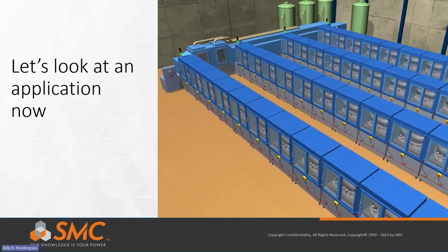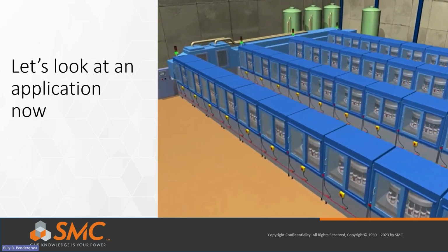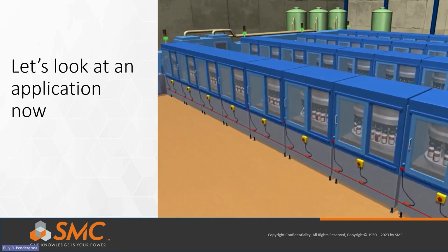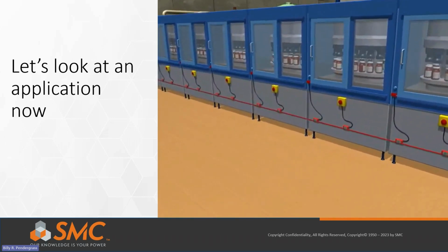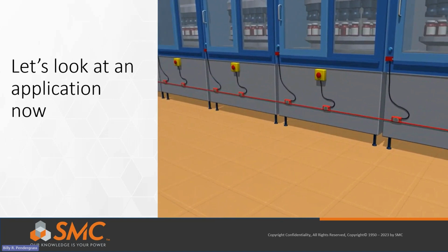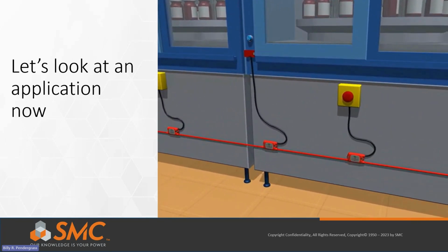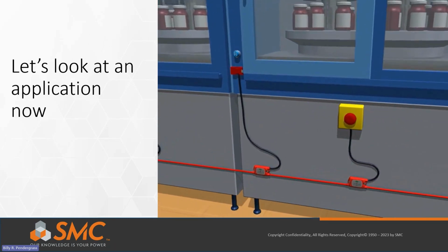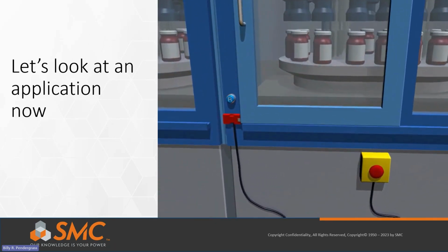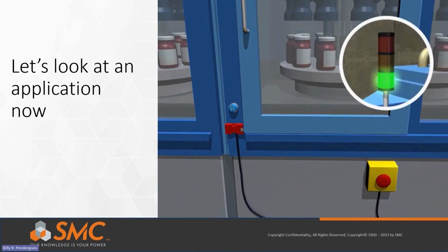If we look at the same scenario, but employ Allen Bradley Guardmaster safety relays and safety components, featuring GuardLink technology, you can access status information for the entire safety system. Connecting all the safety devices through GuardLink-enabled smart taps and standard 4-conductor cabling allows visibility of system status down to the individual guard doors and e-stops.